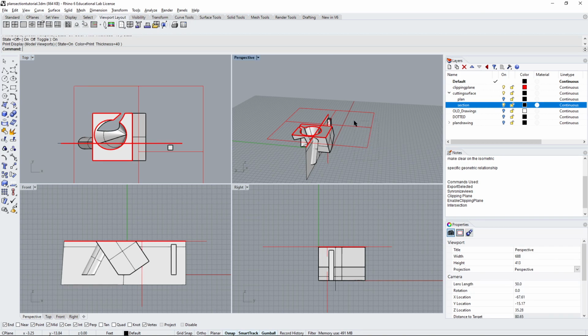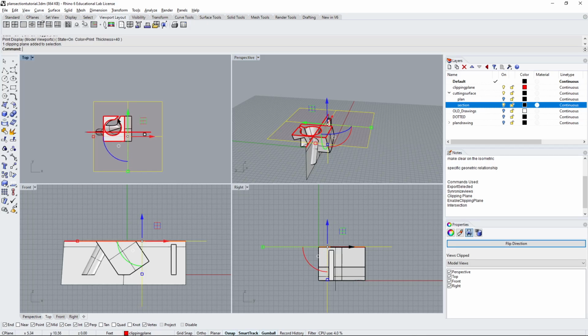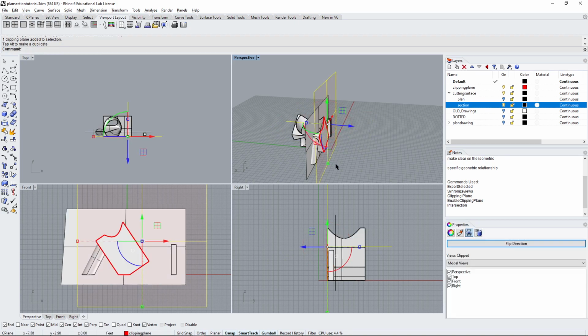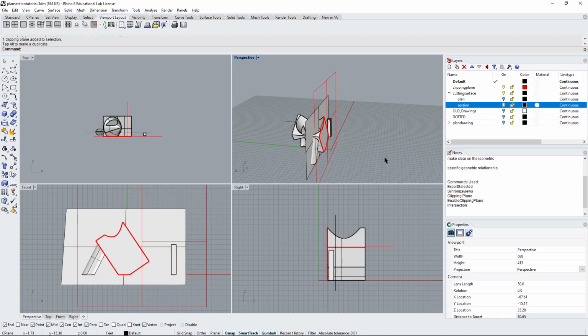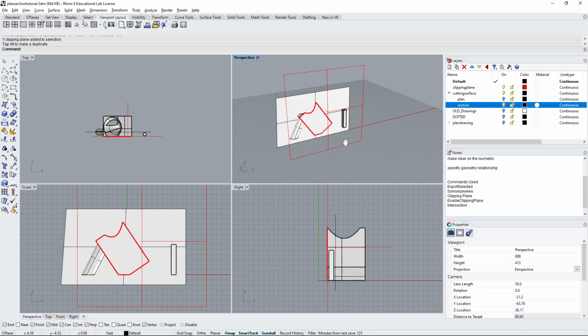So I'm going to take this clipping plane that I've got here. You notice I'm working in plan and section here orthographically, just in the XY plane. This is going to make it so much easier. And I've oriented my object such that it also exists in the XY plane. So I'm going to hold Shift here so that it snaps vertically. And we're going to turn our section cut, our clipping plane, here.